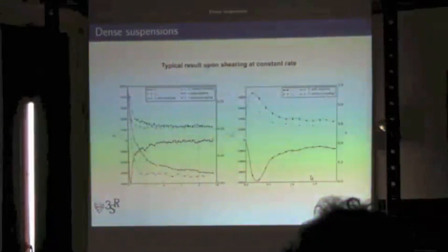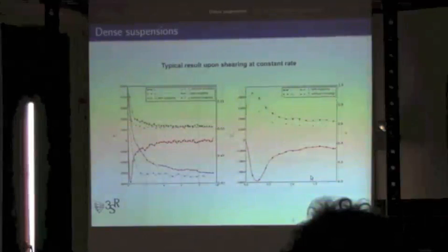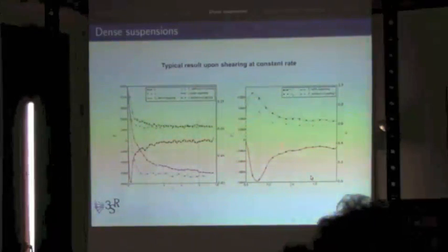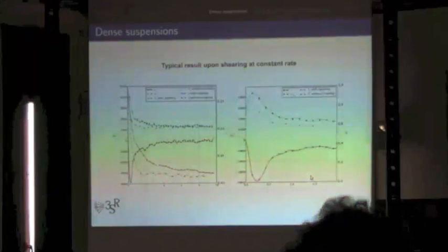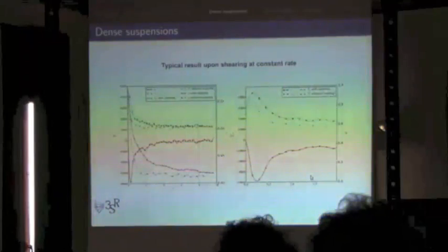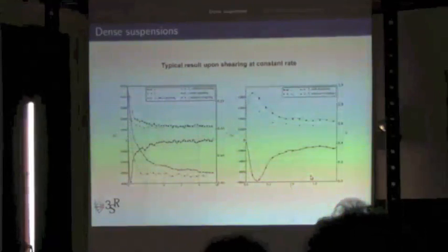This is what you get. So you impose a shear rate and you deform. This is 1000% of deformations. So evolution of stress. On the right hand side you have the zoom. So evolution of stress with total deformation. You have a peak. It happens at the same time as you have a dilatancy in the early stage. When you have dilatancy, you have a negative pore pressure, a suction, which tends to keep all grains together. With time, pressure here goes back to 0.